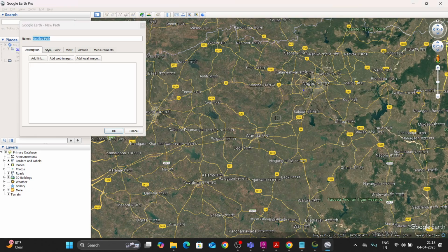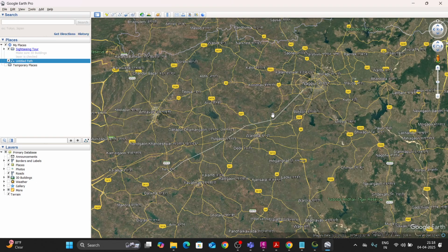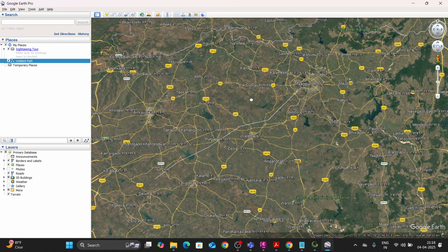For this road, we need the existing surface. For that, we'll consider the area required for this. SRTM will provide the contour lines from Global Mapper. We only need to select the area which we want to develop.